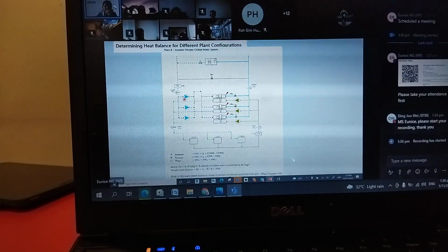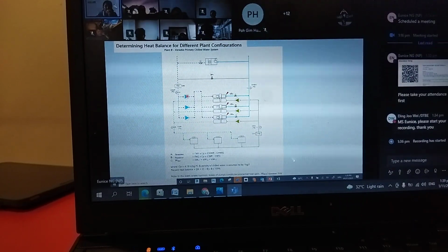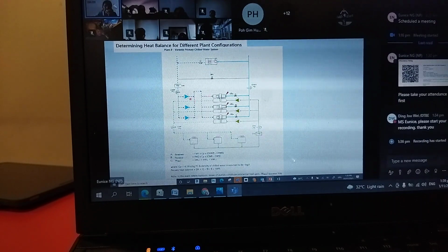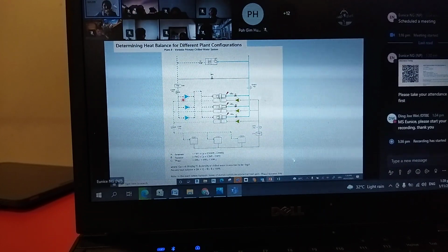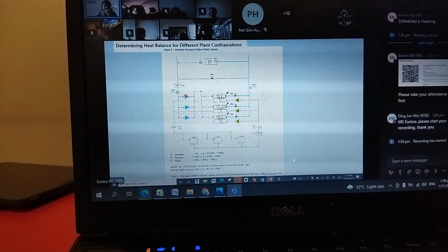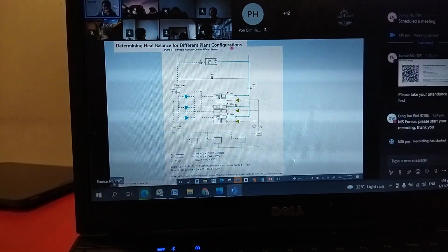So this pump itself can run on variable speed. Again, this pump is sized to meet the critical load path. But the only thing is that when the load is low, this one can run on variable speed, so there is some energy saving. But this pump is again a very big size because it has to meet the critical path.